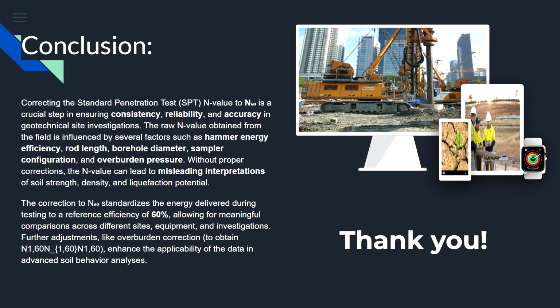Further adjustments like overburden correction to obtain the N'60 enhance the applicability of the data in advanced soil behavior analysis.